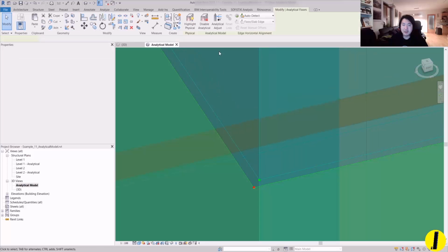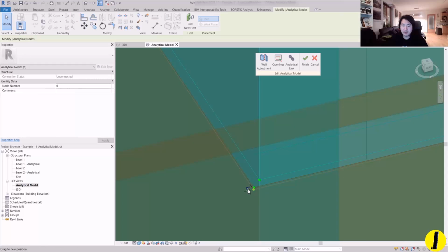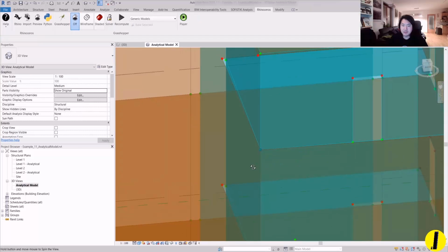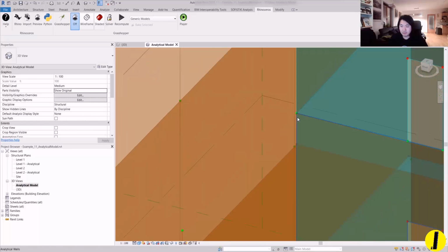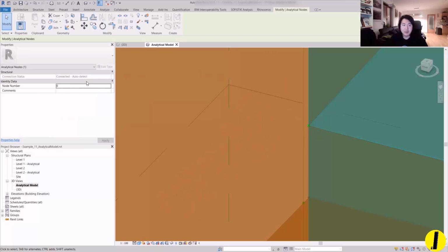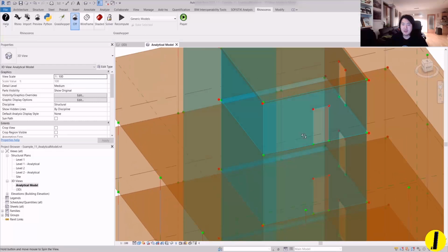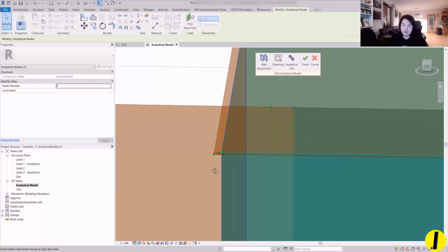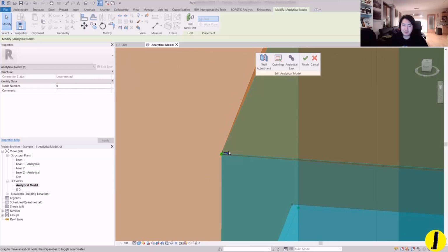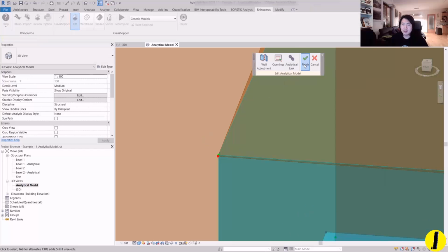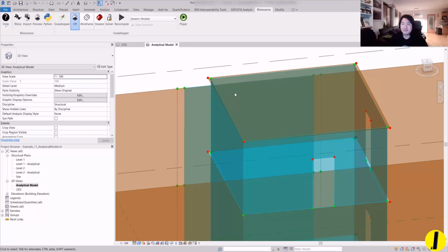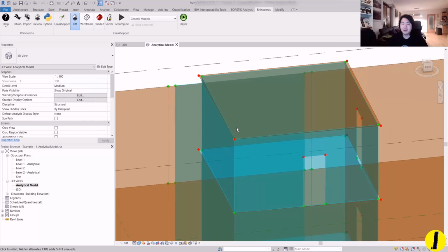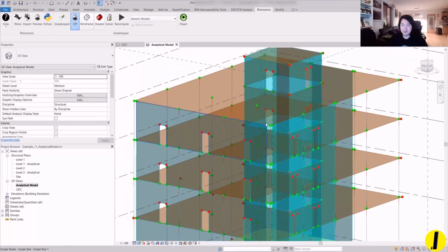Of course we can always adjust the position of the analytical model manually. Then once you connect manually, you may be able to see the blue points indicating manually connected node information. So right now both of them are automatically connected, that's why it's green. But as you can see, when we want to manually adjust this analytical model, it could be really tedious. Luckily it works well, but sometimes it's really annoying. So I wouldn't recommend manually modifying this analytical model unless Autodesk updates it in the future. I wish they would really work on it, but other than that, I wouldn't recommend doing these things.